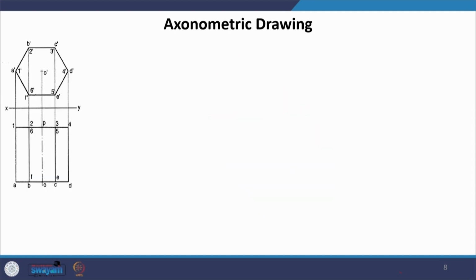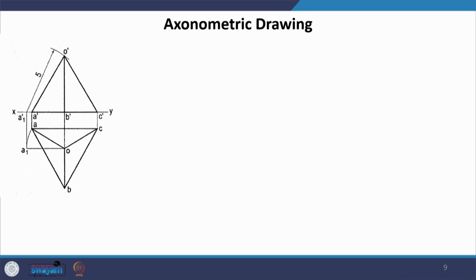This is again very simple. I am not going to redo this. This is a hexagonal prism, exactly the way we did the pentagonal prism. You are going to do that. Start by drawing the plan, inclined at 45 degrees and give respective heights to each of these points. Okay. Now, let us try to draw this triangular pyramid, and let us see how do we start drawing the